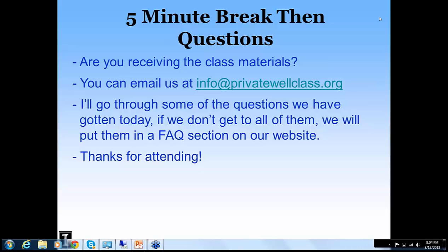So I recommend, if you haven't been through the lessons, that there is, I can't remember which one exactly, but it shows a diagram from, I know, the Minnesota Department of Health that lists all the possible things that could affect your well. Even having your well away from a building. We run into wells that are in somebody's basement, or they put their garage over the well and the well's buried under cement now. Those sorts of things won't allow you to do any maintenance on your pump, or when something fails, your well's probably just going to have to be replaced. And so there's a lot of things to look at regarding that.